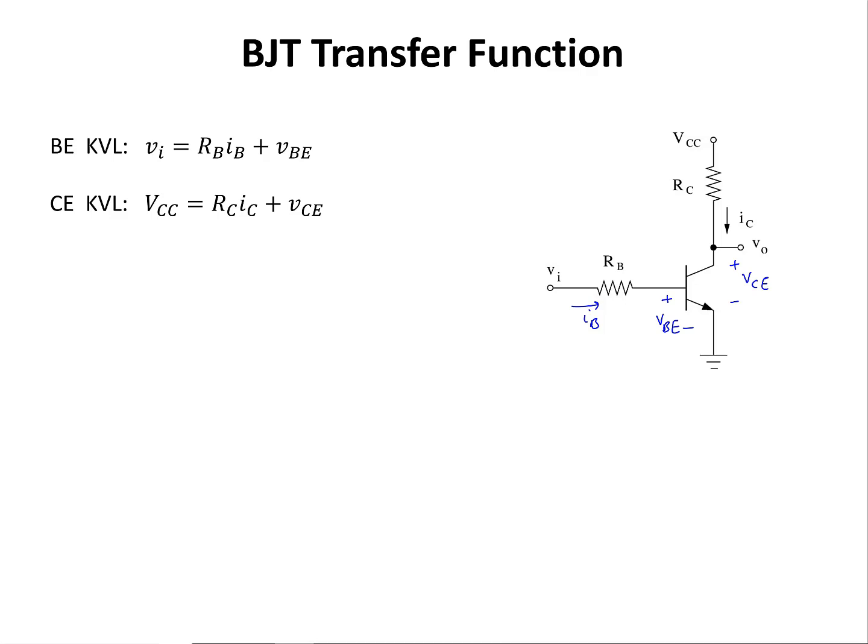Starting with the transistor operating in the cutoff mode, I'm going to write case 1 is when BJT is in cutoff. That means I base is equal to 0 and V base emitter is less than VD0. Also, I have I collector equals to 0 and I emitter equals to 0.